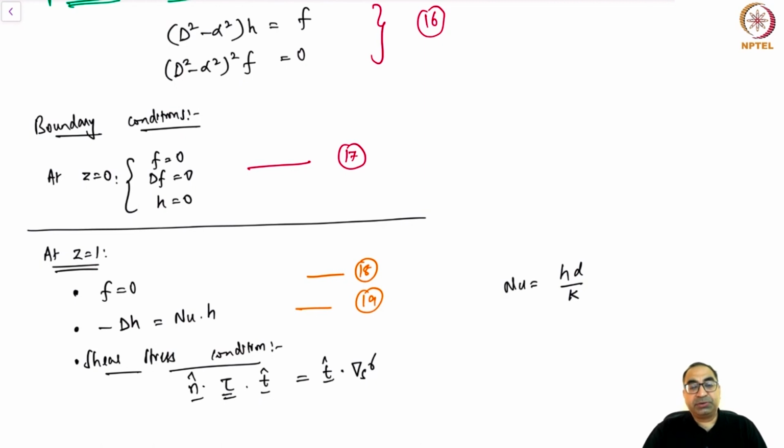Now it's important to note that the temperature on the interface is not necessarily fixed at T0, meaning the temperature at the interface just below the fluid can be different from the value T0 above. This equation involves a new non-dimensional number called the Nusselt number. We will examine the different limits of the Nusselt number later in the lecture.